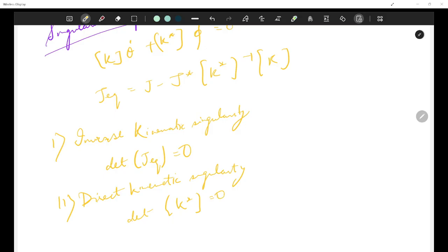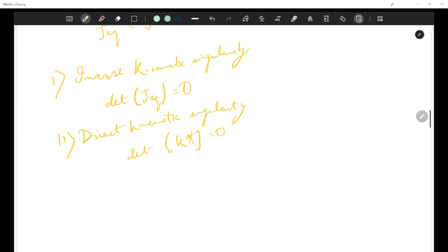This is important. This implies that the constraint matrix becomes singular. Robot loses stiffness. Platform can move even when actuators are locked. Okay, and yeah, so in many cases it would be dangerous. But yes, this is the example.